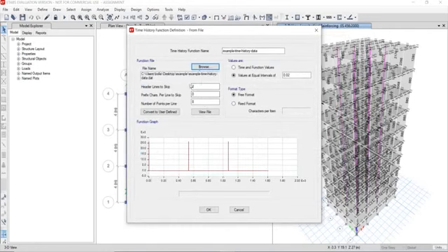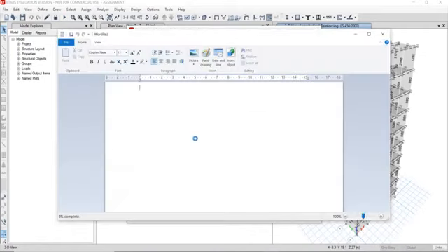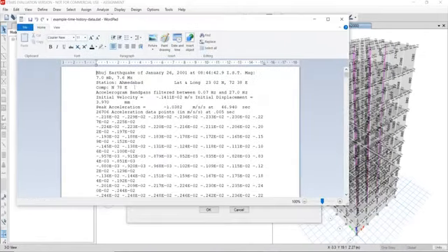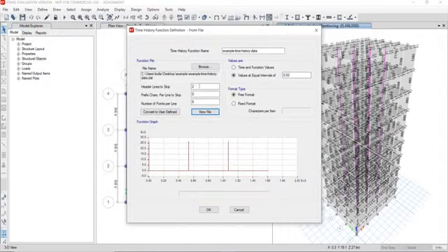As we entered our file, first view the file. Just see how many lines the header is. 1, 2, 3, 4, 5, 6, 7, 8, 9. 9 lines is the header. So keep 9 here, and the number of points per line in our file is 1. So make it a fixed format, and enter 10 characters here and then click OK.